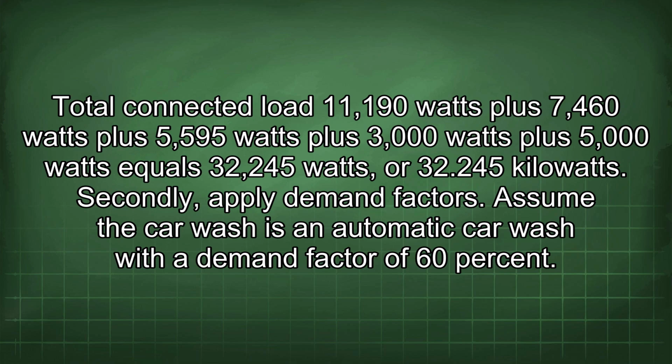Total connected load: 11,190 watts plus 7,460 watts plus 5,595 watts plus 3,000 watts plus 5,000 watts equals 32,245 watts, or 32.245 kilowatts.